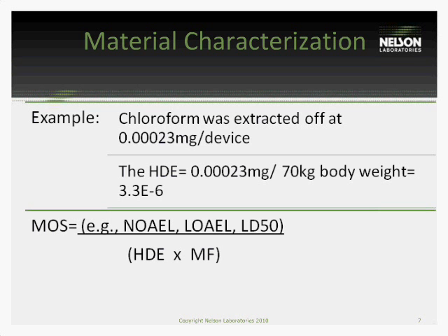So now that we have that daily exposure, we can do a quick calculation where we get some toxicological data. We're looking for NOELs or LOELs. They're basically levels where we see no observed adverse effects of that compound in clinical data. And then we might have to multiply that human dose effect by some modifying factor depending on the quality and type of data we get.